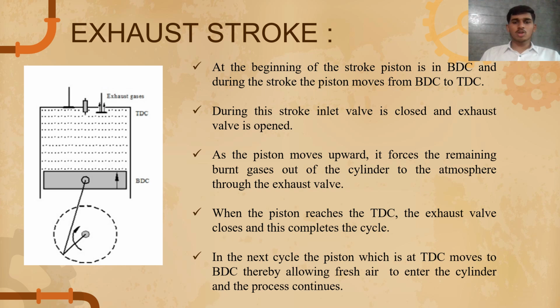So finally, the exhaust stroke. At the beginning of the stroke, the piston is at the bottom dead center, and during the stroke, the piston will move from bottom dead center to top dead center. During this stroke, the inlet valve is closed and the exhaust valve is open. As the piston moves upwards, it forces the remaining burnt gases out of the cylinder to the atmosphere through the exhaust valve. When the piston reaches the top dead center, the exhaust valve closes and the cycle is completed.